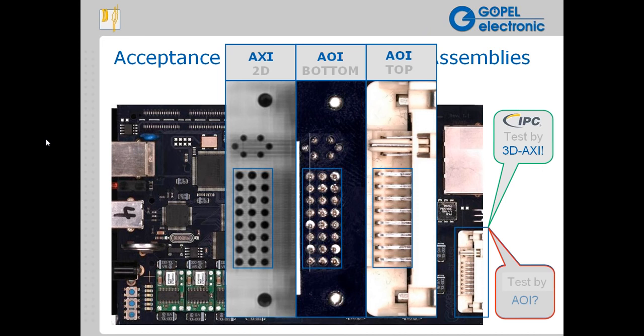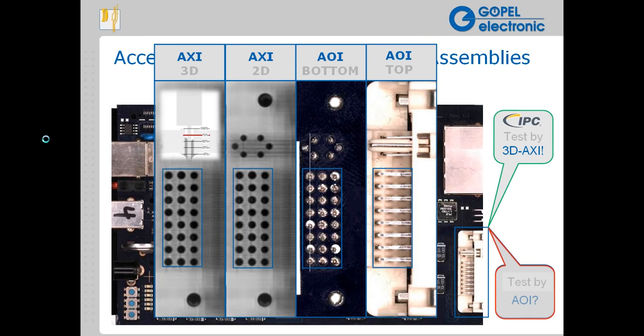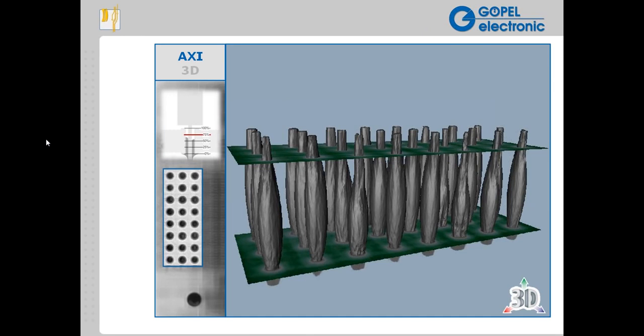And if you look at the X-ray image on the left, in the third and sixth rows, you can very clearly see examples where the hole is not properly filled with solder. So those are potential dependability issues down the line. And in many applications for high dependability electronic assemblies, this can be a very critical consideration. So this is an application where X-ray is very clearly needed and very clearly useful. It illustrates something that is really not detectable in any other practical way.